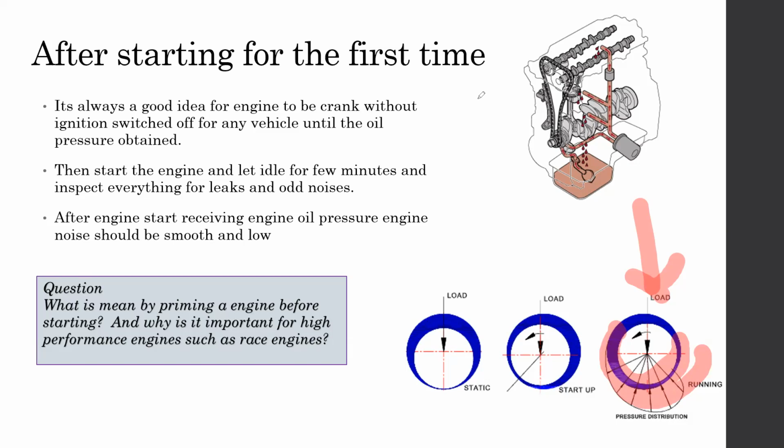But if you go to a dry sump lubrication system, in some cases they come with an inbuilt electric motor that can turn the complete lubrication pump in order to provide high pressure oil to all the components before starting the engine. This is very important for dry sump engines, because they are usually fit for vehicles used in high performance applications, and their tolerances are very low.